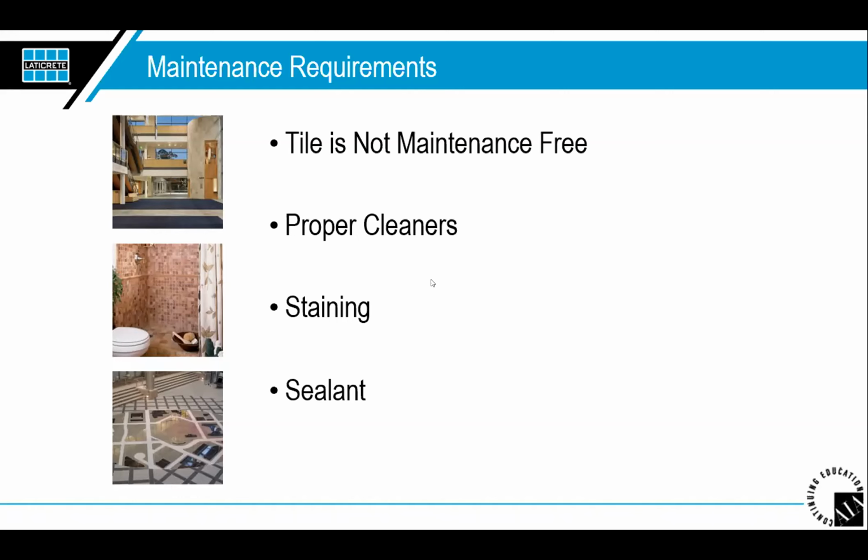Thanks. Okay, cool. So again, what we were just talking about, the maintenance requirements. Tile itself is not self-cleaning, and it does require maintenance. Proper cleaning techniques are very important to the long-term success of any tile installation. For instance, the acids that we were just talking about are not recommended for Portland cement products. Generally, we just want to use neutral pH cleaners. That's sufficient for everyday use, and it's not harmful to us or the environment itself.